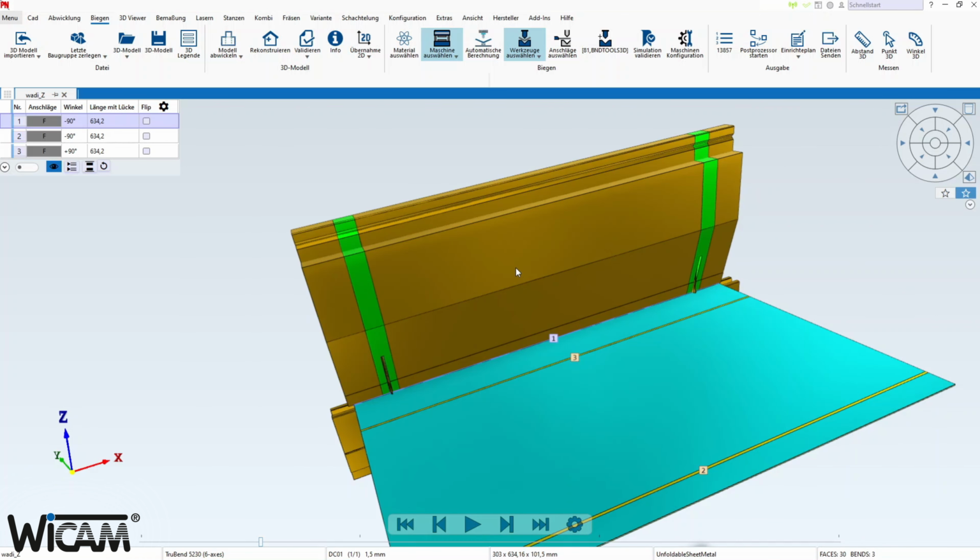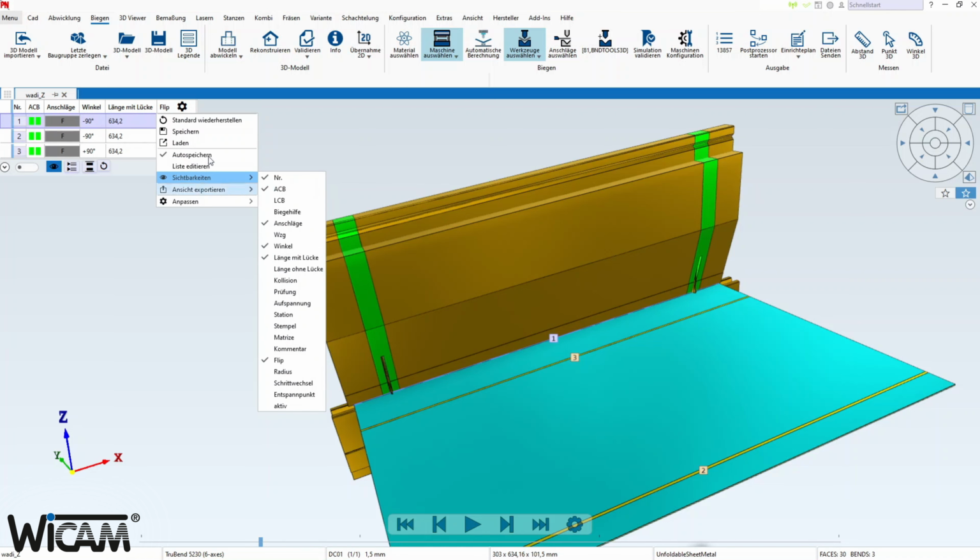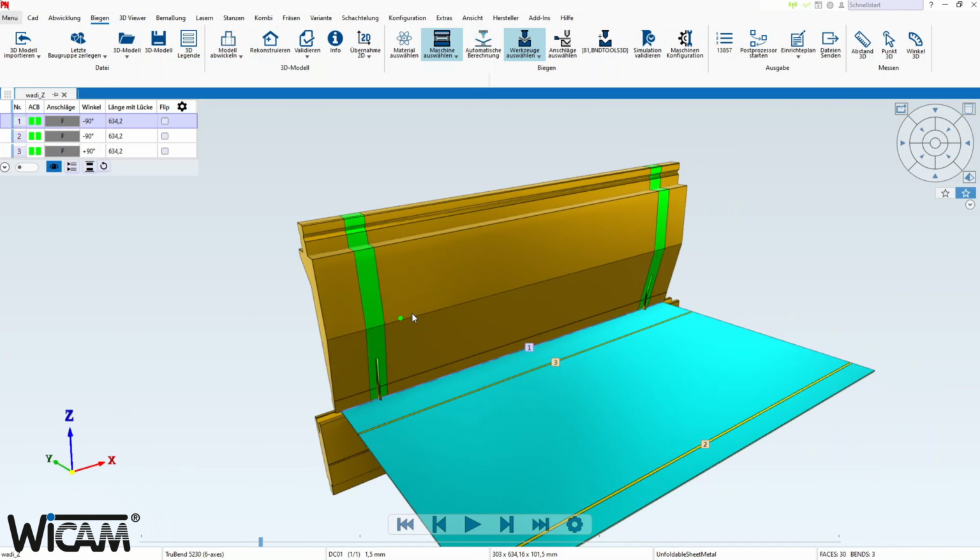The calculation tool can then automatically recognize whether such a measuring tool may be used or not and can then be automatically activated or deactivated. In our information list above, we also have the smart option of activating the ACB tools feature. So we can see for every bend, whether an ACB tool is being used and whether it is currently activated or deactivated. Also, we can then simply with a single click at the top of the ribbon, activate or deactivate the ACB tools.